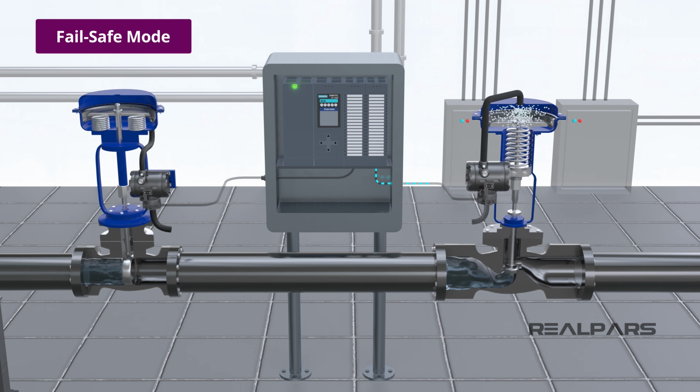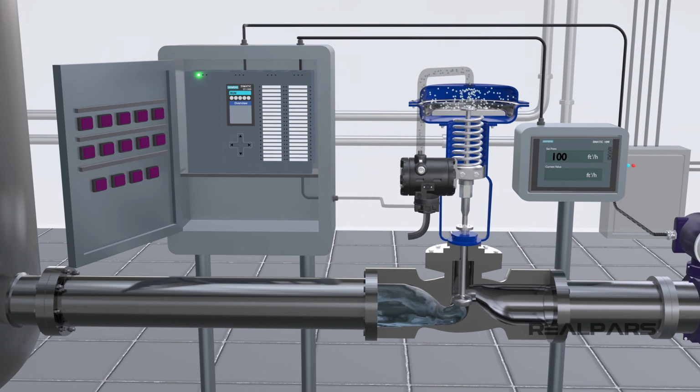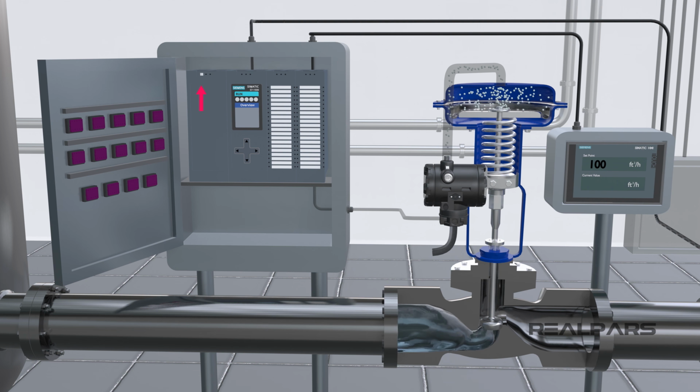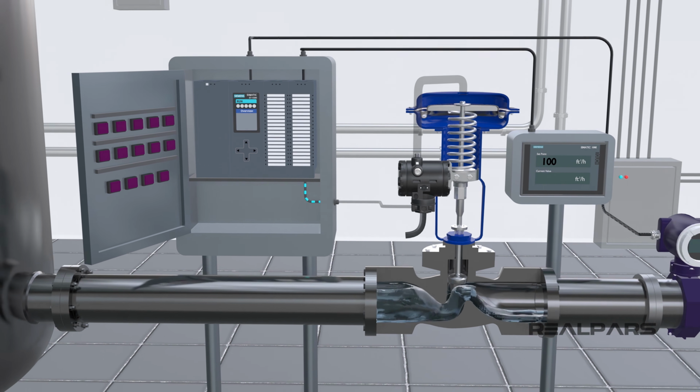The actuator causes the valve to open in a fail-open control valve. In normal operation, the force of the spring must be overcome by the electrical or pneumatic actuator. In the event of a power failure to the actuator, the electrical or pneumatic force is no longer present, and the spring pressure forces the valve to open.